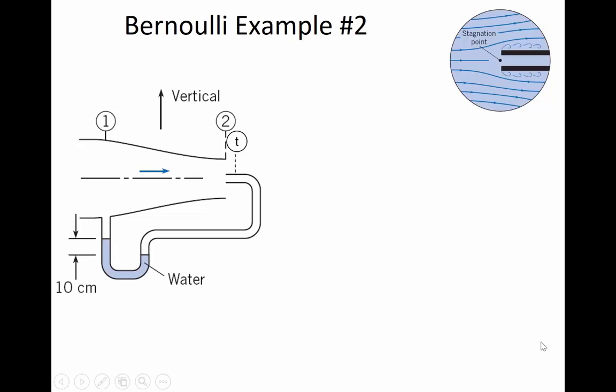Okay, so as the flow is going from 1 to 2, the energy is constant, it's just changing form. So we had low velocity here, but high pressure at 1. And then as the velocity increased, some of the energy changed form. So that energy that was existing as a lot of pressure before, some of it went over to additional velocity head. So at 2, there's still the same amount of energy, it just changed form. Now, at the opening of that stagnation point, what we see is that there's a streamline with a dead end.